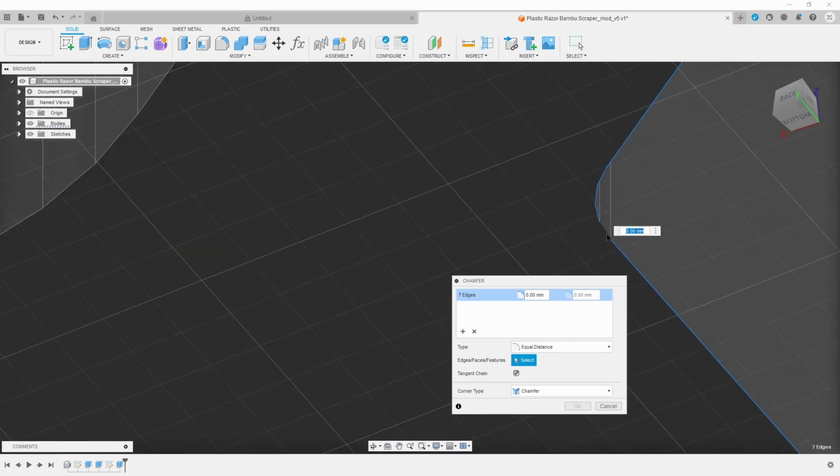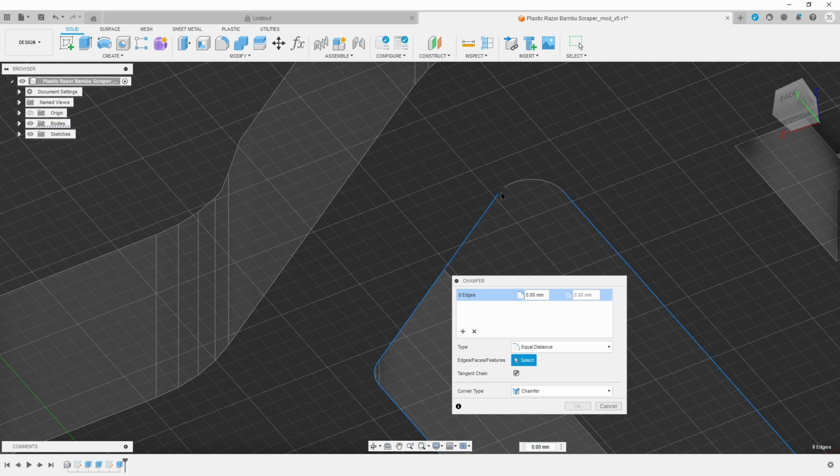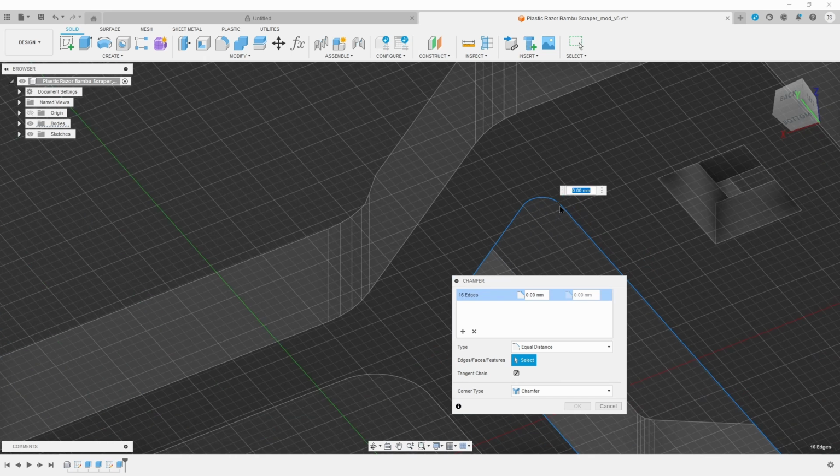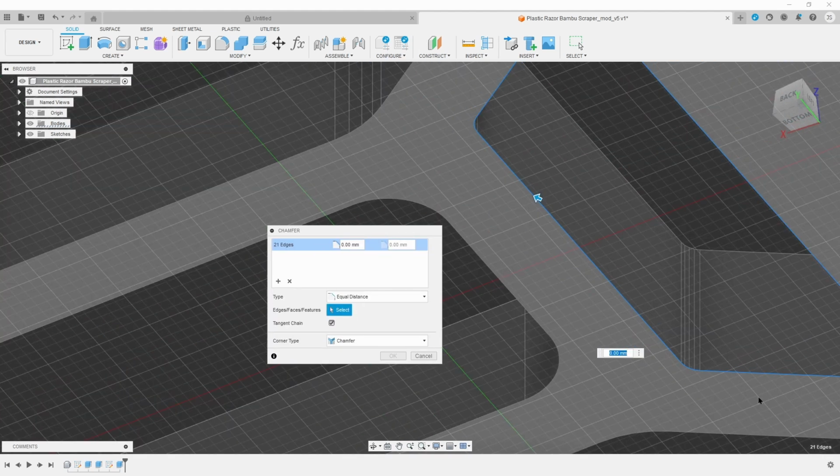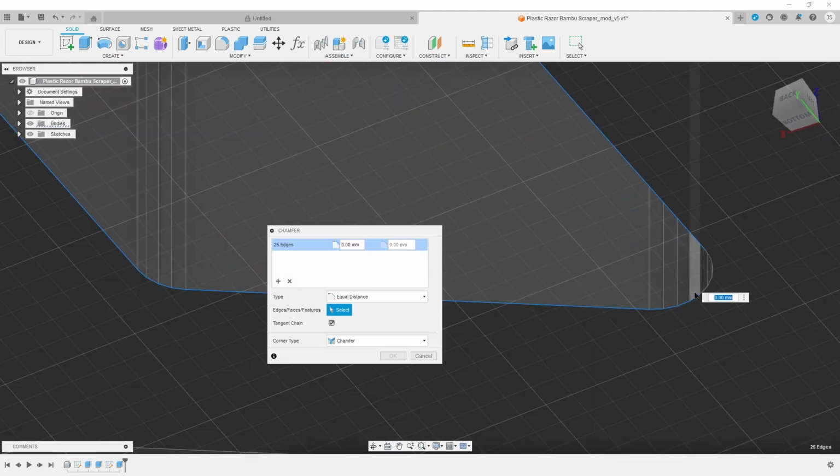Here's the problem with this way of doing this: because this step file has limited radius, it's not the complete smoothest curve, you have to go through and select each segment in that.